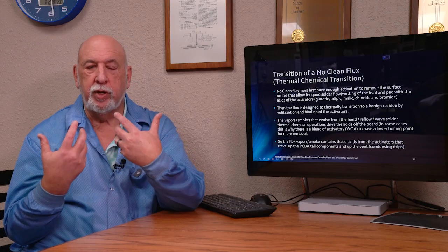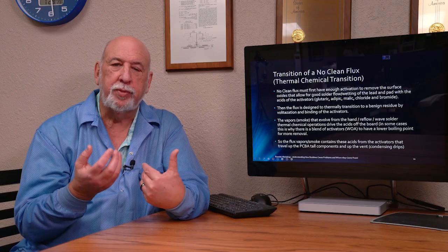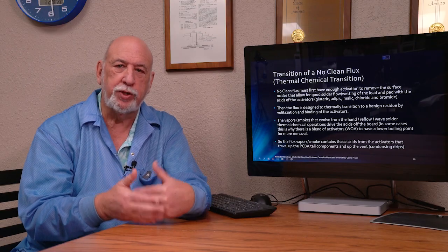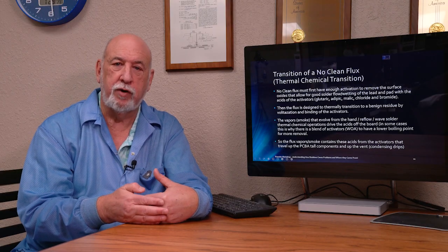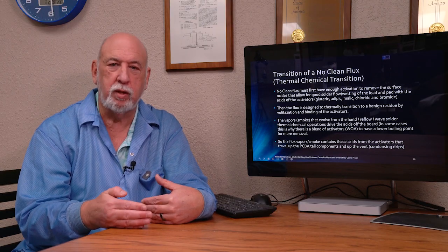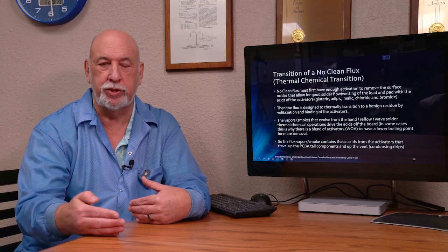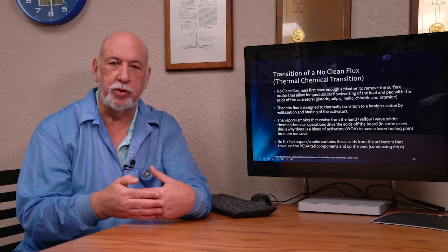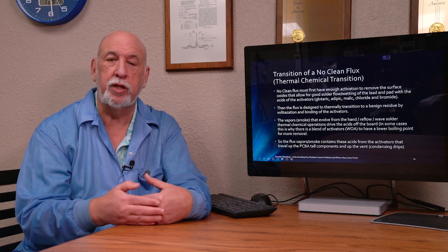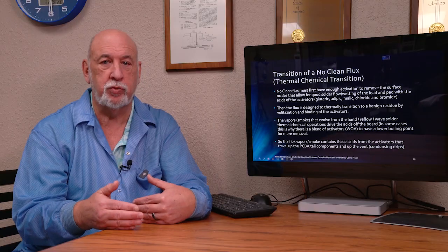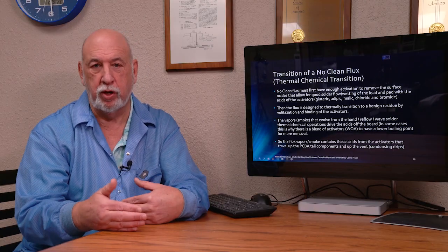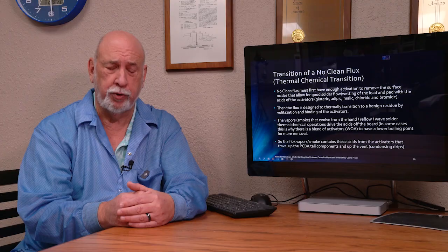Traditional no-clean fluxes are designed to be insulative protective residues, but they only are insulative protective residues when they reach a certain transition state. When the material goes from a soft, gooey material to a hard crystalline material, we can actually measure the resistance differences in those materials. We can see a 4 to 5 decade drop in surface insulation resistance between a hard crystalline material and a gooey material, which we published on before. So if you're interested in that kind of data, give me a call.